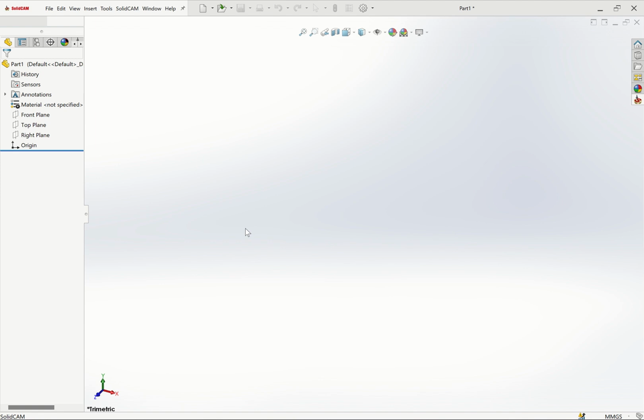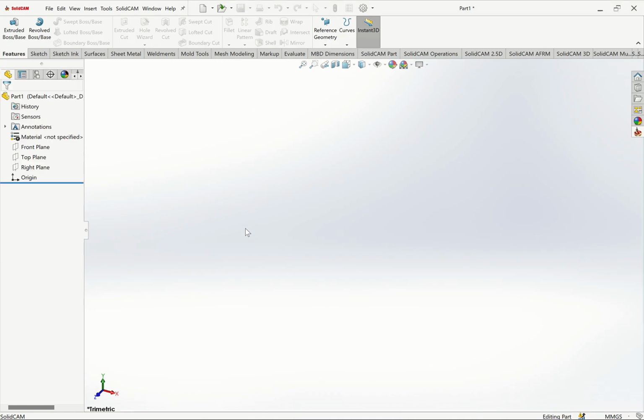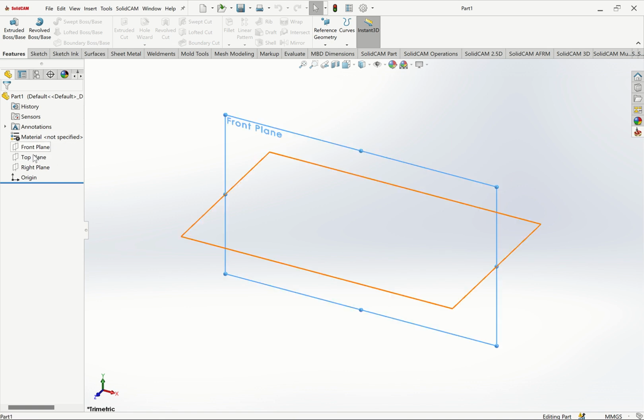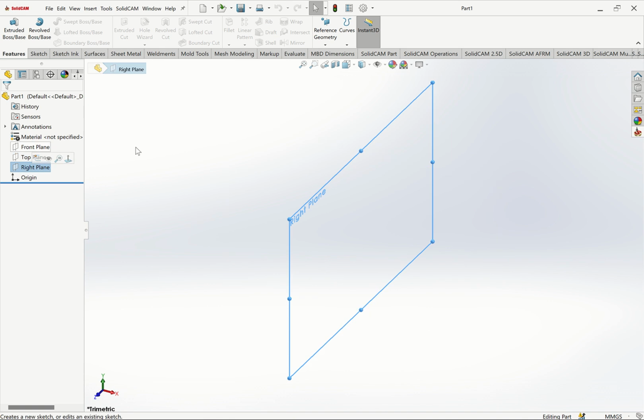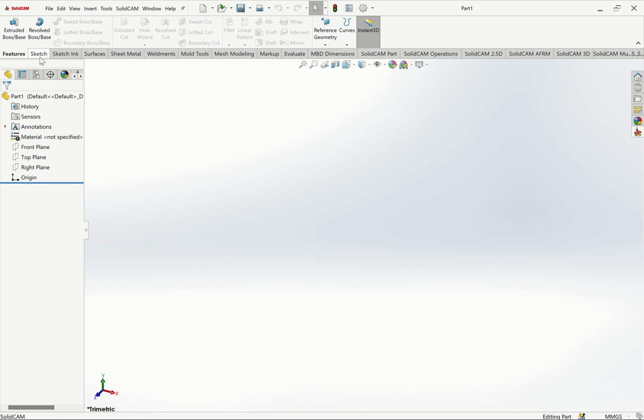So we are going to look at an introduction to 3D sketching and also adding what you call a composite curve, using the composite curve to convert sketches into one curve. At the same time, we will be using sweep commands to do our design. So basically for 3D sketching, when you are selecting these planes, it means you're using 2D sketching. But as we're going to do 3D sketching, how do we do it?